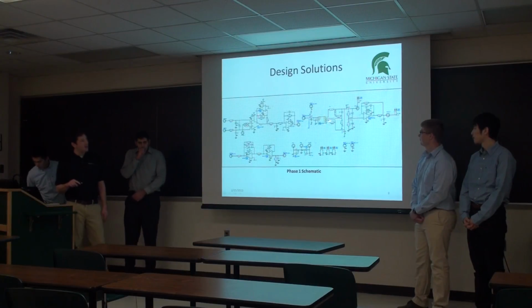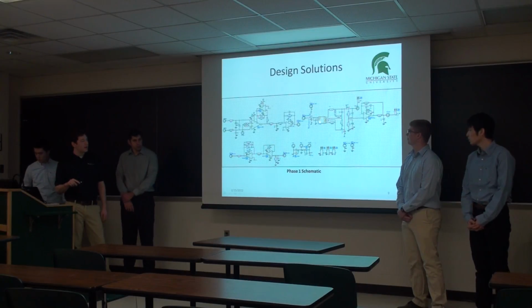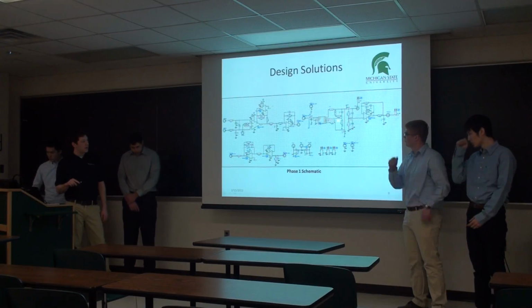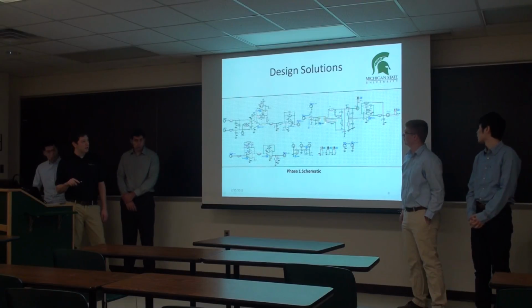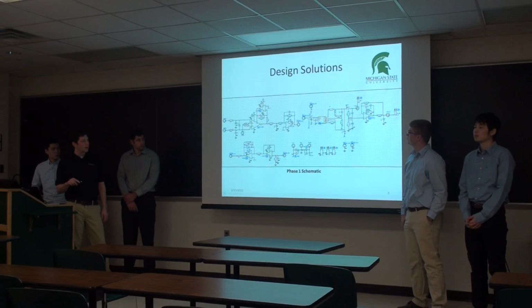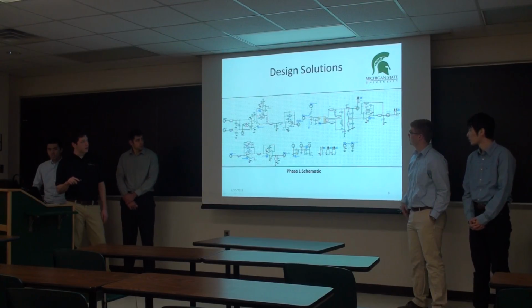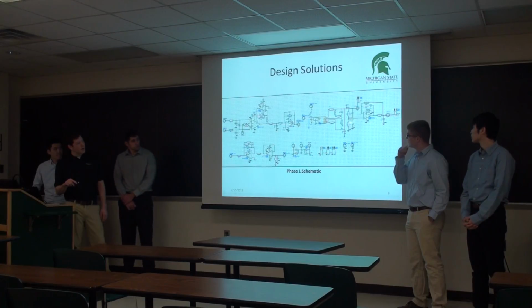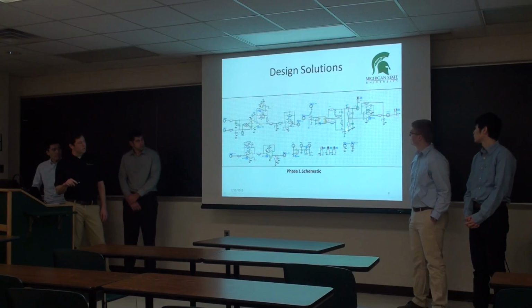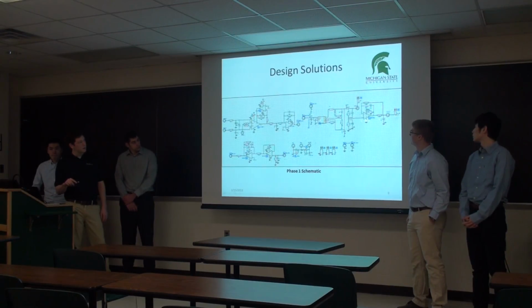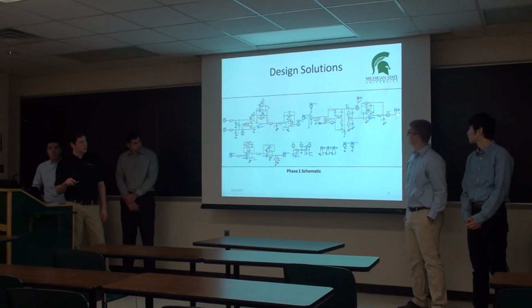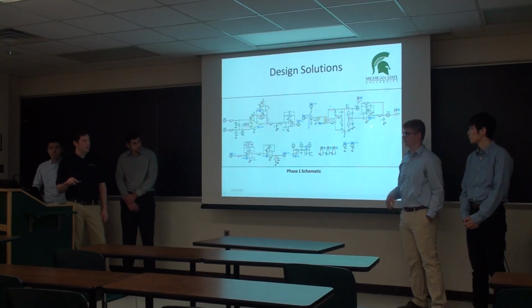And then after that, around the buck converter, you have to set its switching and all the settings for it with this circuitry around it. So we have an inductor and other things around here. And then through here we have the divider and a little bit of filtering with the capacitors, which will go to this filter, and that's where the 2.5 volts will come out, hopefully as clean as we can get it.